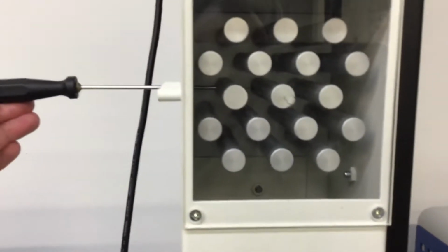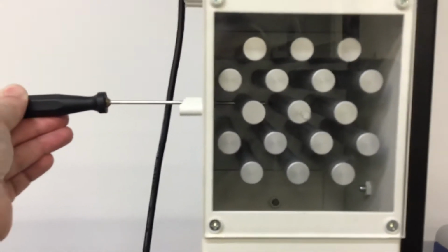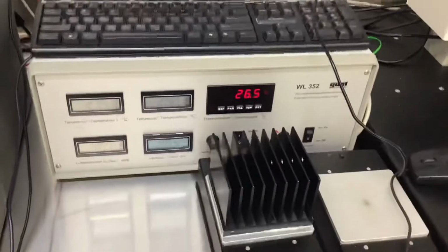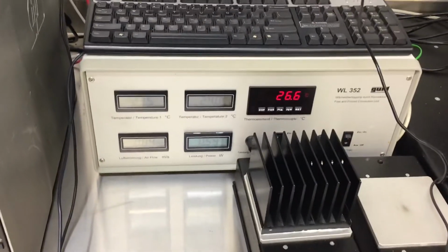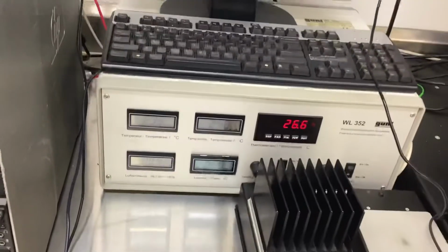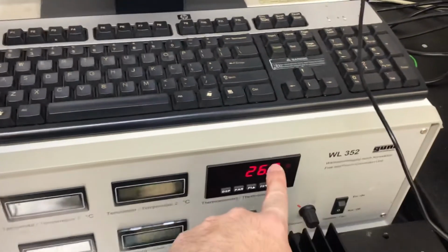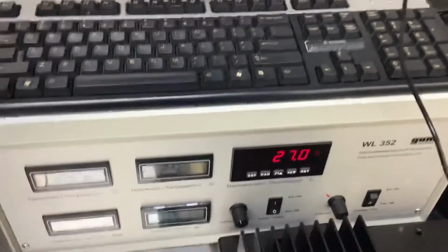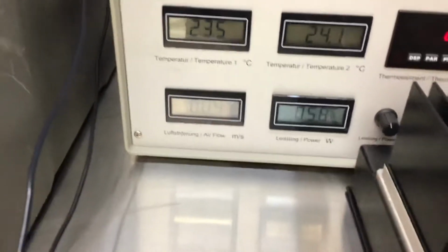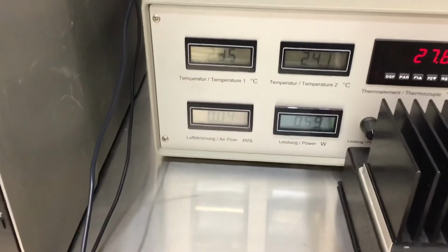Okay, if you wait enough time, you're going to start to measure the surface temperature. You can see now the value increased to 26 by just holding this around 5 to 10 seconds. So the data that needs to be collected here are temperature before and after the heat unit or the heat exchanger unit, okay? Surface temperature, that is by direct contact, and students need to place this in the right place. And power, where you set it up, you need to know how much heat is actually going into the system. That's electrical power. And the flow rate.